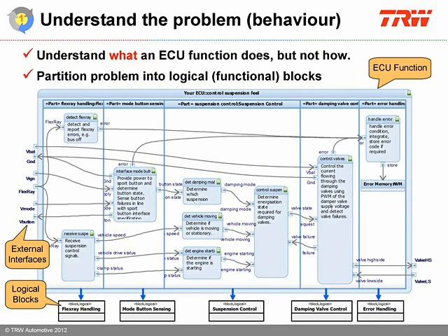In SysML, we model the functional behavior of the ECU's functions using activity diagrams. An ECU function is broken down into a set of atomic activities that are not solution-oriented. The flow of control and information between activities is depicted, and swim lanes are then used to allocate the activities into logical groupings.